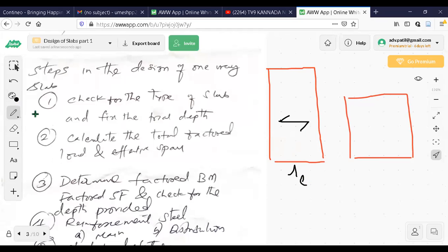Now you look at the other diagram. It is a likely candidate for a two-way slab because it is almost squarish. In the one-way slab, the bending takes place only like this. It bends only in this way because these are the two supports. All 4 supports are there in a two-way slab. Not only does it bend like this, if you look from this side, it bends just like a saucer, cup and saucer. Saucer you have seen, cup and saucers. A two-way slab becomes like a saucer.